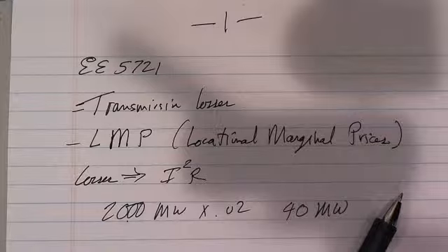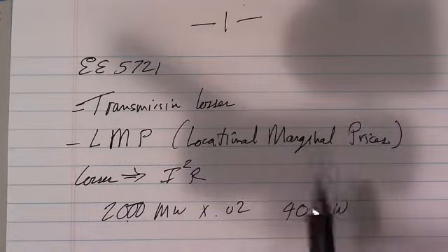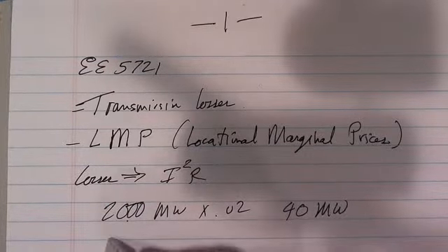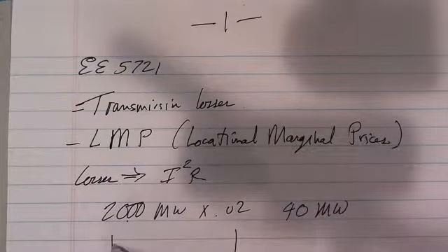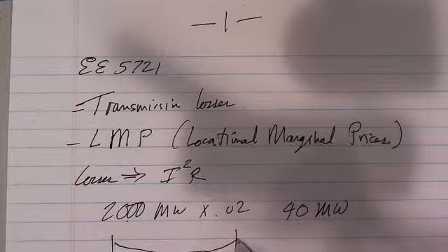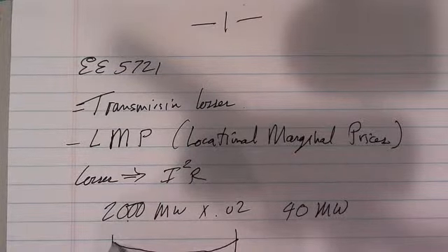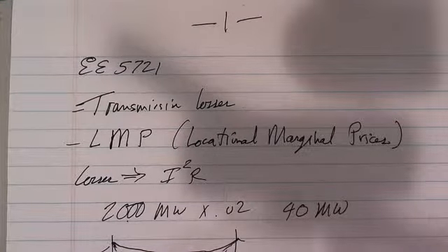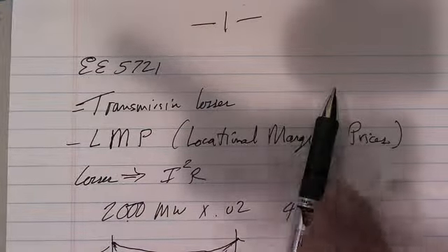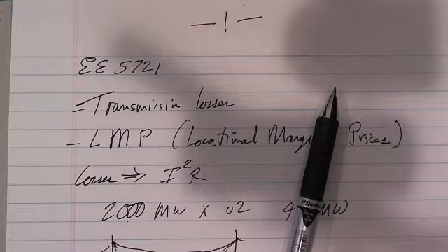And what we say is, for transmission lines, they sag. So here's a transmission line, and it normally goes down a curve like this, which if you remember your statics, it's a catenary curve, and you heat it up, and the line gets like this, and you heat it up some more, and it goes like that. And if you got yourself a little tree down here, before you know it, there is an arc.